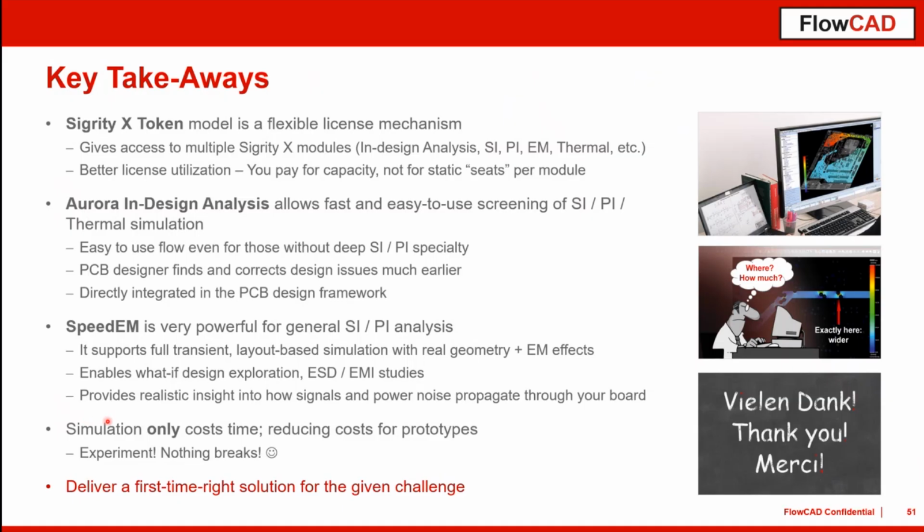So let's get straight to the questions I have here. Can you please tell us something about hardware that is recommended for simulations? Oh, yeah, the more the better now. I did all these analyses with my notebook. This is not an office notebook, but more like a workstation that can be used also for your layout tools. So you do not need a high-end workstation or server that might be used for a 3D EM analysis. Typically, such a CAD workstation should be quite enough.